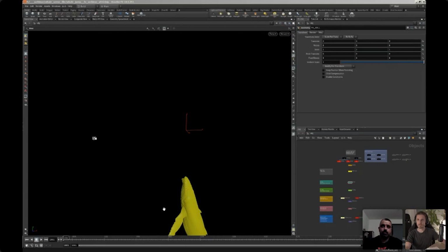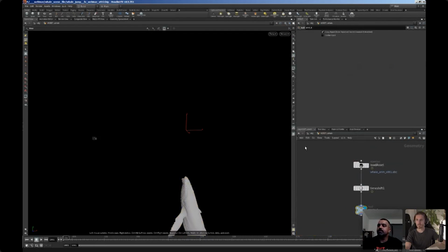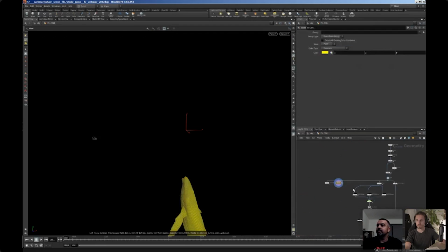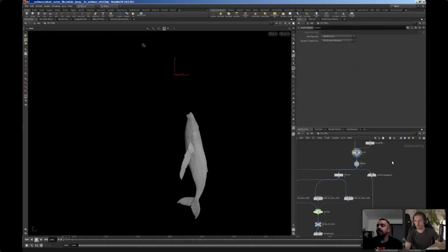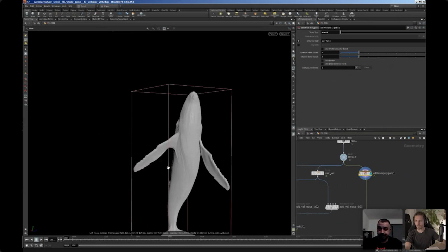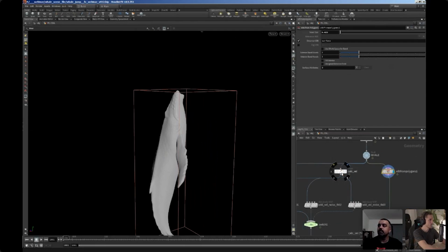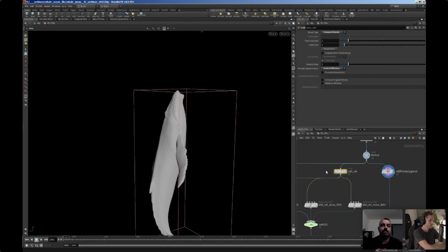And then the first idea, like I said, is taking the asset and preparing it to be watertight, so that there are no problems later on. When you go VDB from geometry, everything works perfectly, there is no hole, so then you are okay and stable. The next thing is to calculate velocity. This asset is simple, but as a base it's ready to go into our tank simulation.